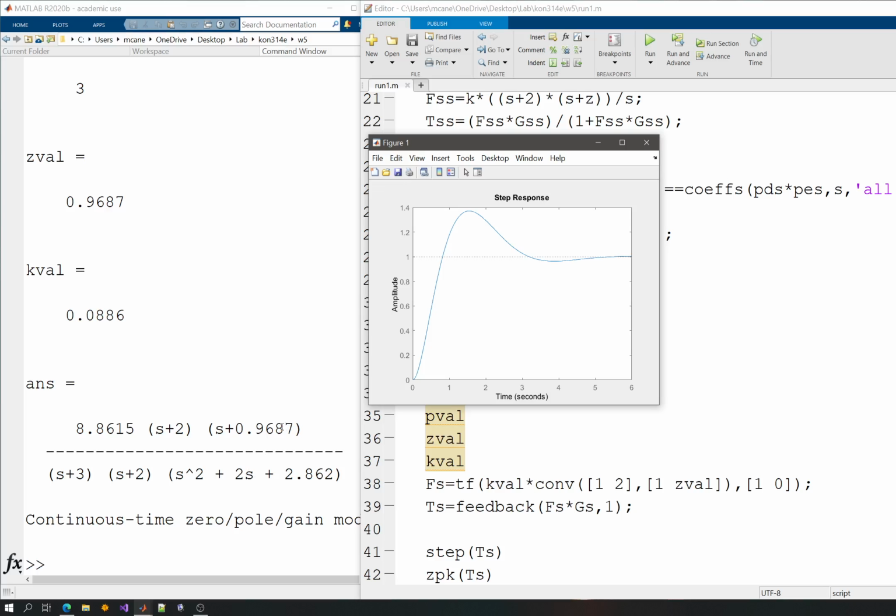This gives me also the real part of that, and I have also a 0 there, which is not ideal. I have a pole-zero cancellation, and I have another pole which is at -3. So basically this overshoot is directly explained by this 0 here, which is in the dominant region. And I said that zeros in the dominant region are not that wanted and are dangerous, in fact. And you can see that here. I don't have 10% overshoot, I have almost 40% overshoot, which is not that ideal.